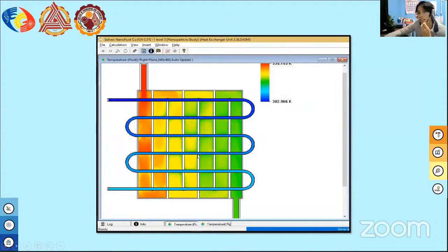The simulation aspect of the study will be carried out through the utilization of the SolidWorks Flow Simulation tool. In order to come up with the different nanofluids to simulate in the program, we use the application's engineering database that allows users to create various types of items with defined properties. To create a new type of fluid, in our case a nanofluid, properties such as density, dynamic viscosity, specific heat, and thermal conductivity are needed at least to define a fluid. Such properties were taken from the calculations made using the equations and correlations.